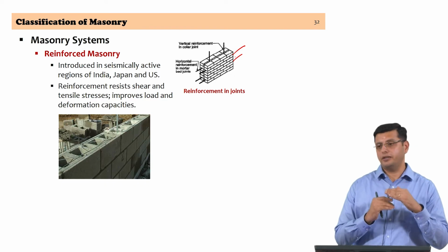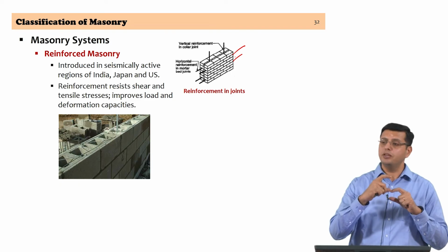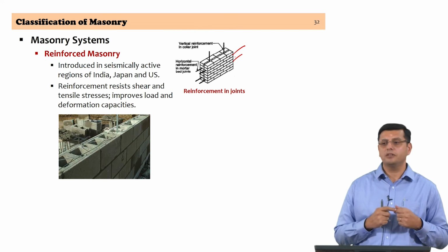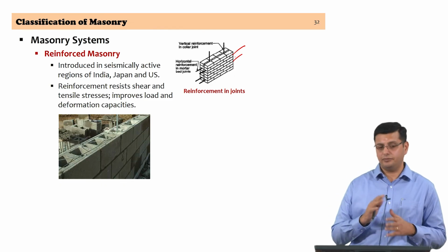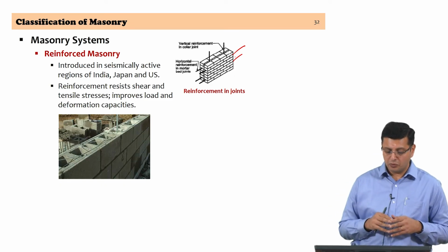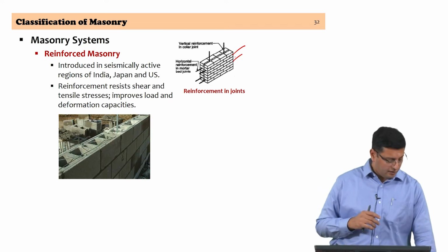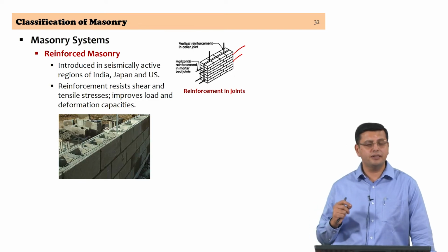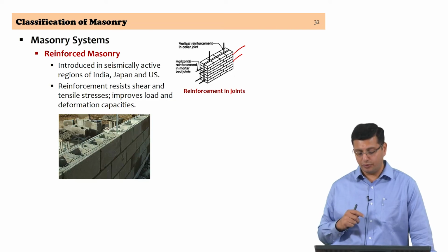that is required for the joint is going to be significant enough in comparison to the height of the brickwork layer itself, and this is a problem in terms of achieving good compressive strength of the masonry itself. So, that is a challenge when you want to place reinforcement in the joints. You cannot even reduce the mortar thickness in the joints simply because you need corrosion protection for the steel that you are providing.